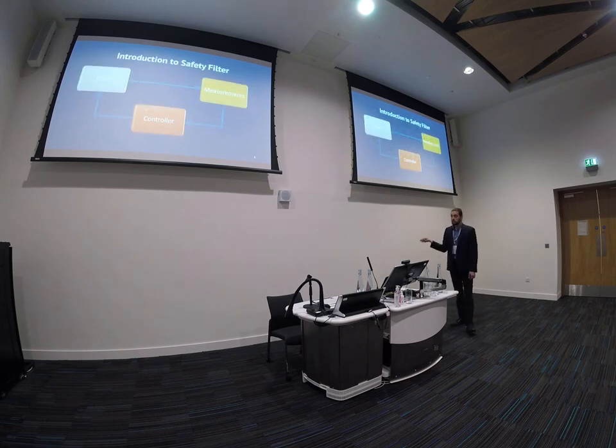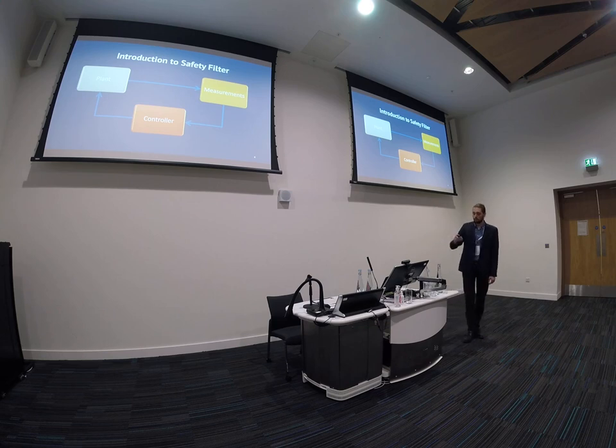So to date, most of the control design that we've seen in the airborne wind energy literature has been focusing on performance optimization. It follows your classic feedback loop, where we have our controller taking measurements and determining control input, and then simply applying that to a plant.